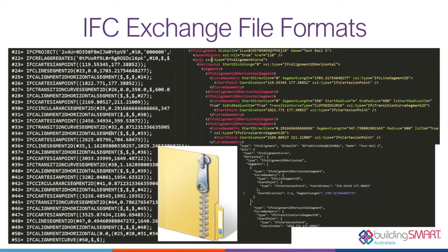You do have one alternative option, which is Geometry Gym provides an alternative IFC importer, which can work in relation to shared coordinates. So you can establish a shared coordinate in your project file and import that way. The only other way, as I said, is to establish a local base point in the 12D model and try and export relative to that. And then that model geometry, if the base point is in a common position, should come in local to the Revit origin as part of that workflow.